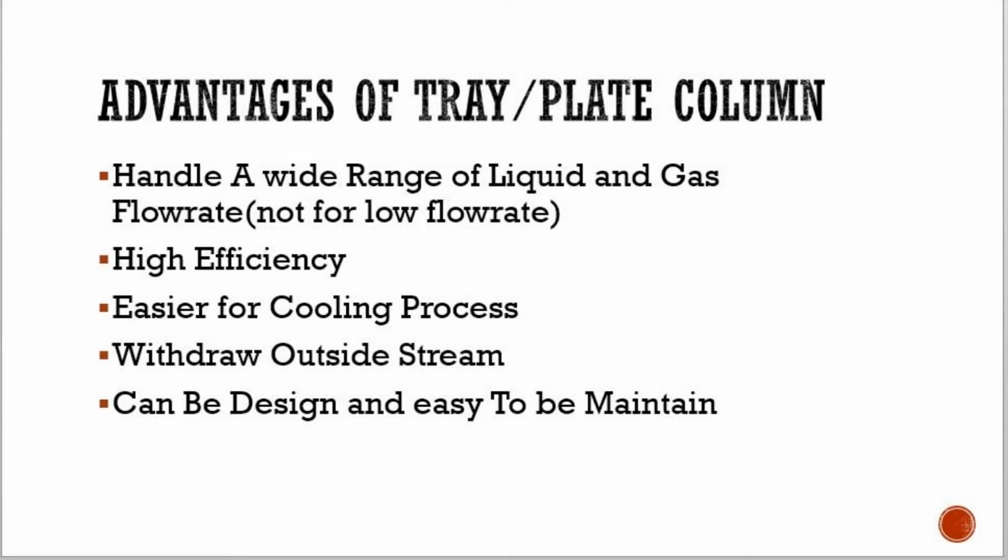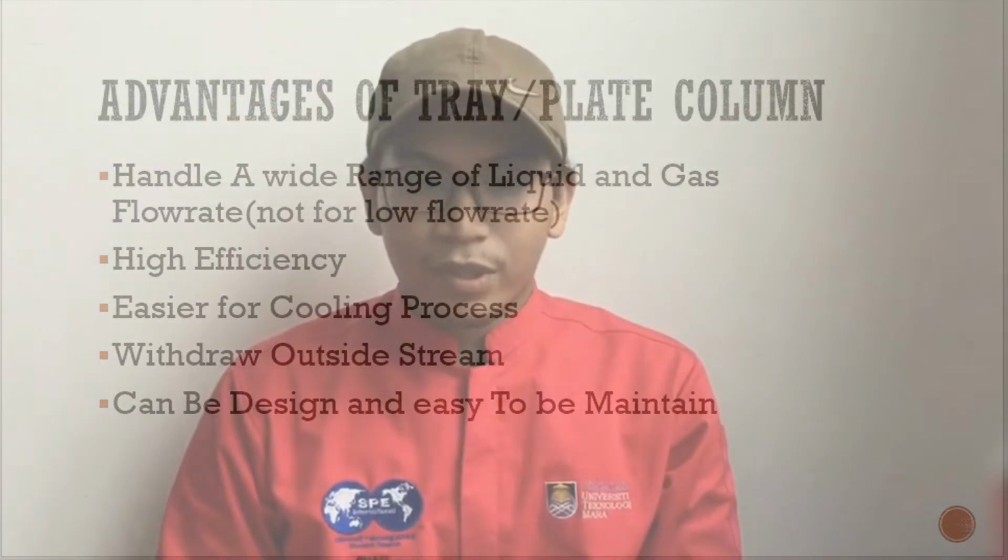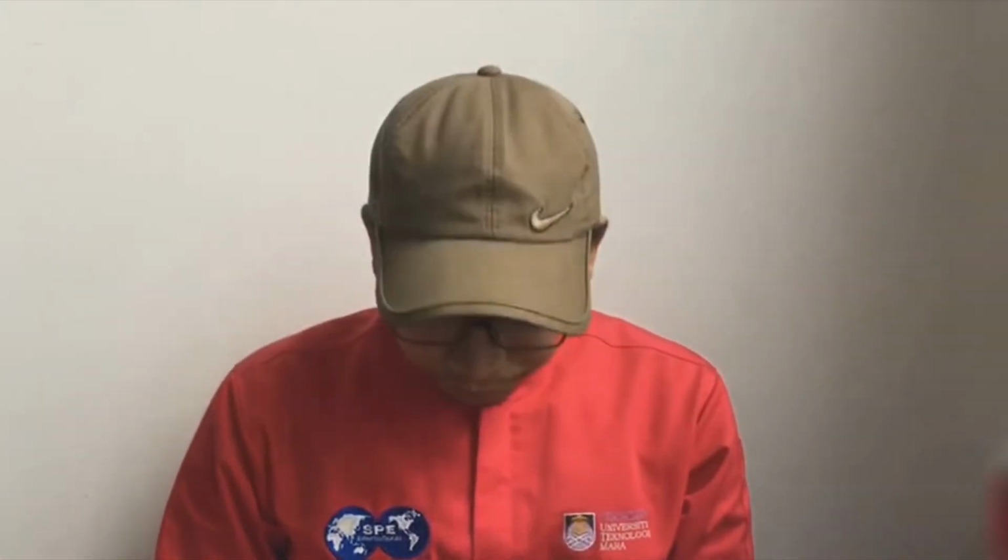It is also easier to withdraw side streams from plate columns. And lastly, plate columns can be designed with more assurance than packed columns. There is always some doubt that good liquid distribution can be maintained throughout a packed column under all operating conditions, particularly in large columns.